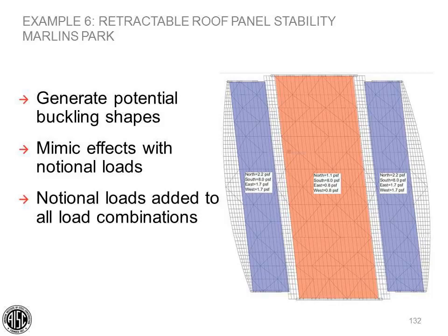Okay, thank you. The next question, back to notional loads. How does applying a notional load of 0.002 of the gravity load relate to an h/500 displacement when we apply the notional load without regard to the frame or column stiffness? Why don't we just force a displacement of h/500 in the model?